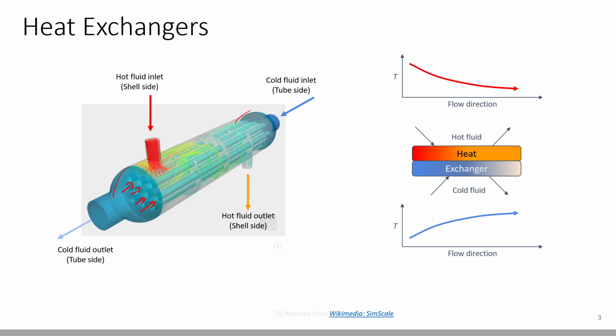However, there are a few thumb rules that you can look at while deciding which fluid should go via which route. For example, in this diagram, I have shown that the hot fluid is passing through the shell side and the exit is shown over here, whereas the cold fluid is entering via this side through the tube and exiting via this.